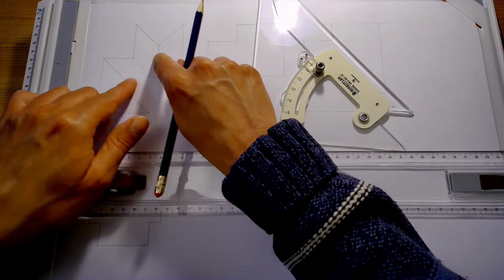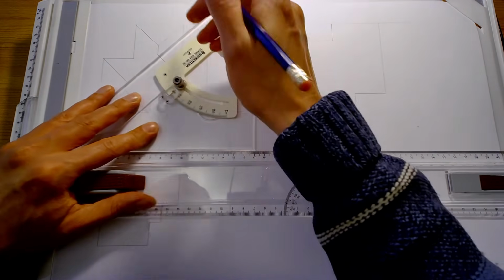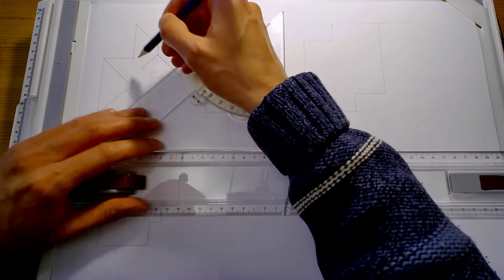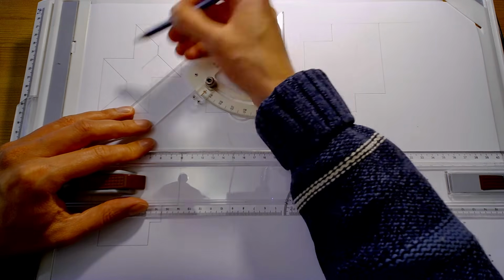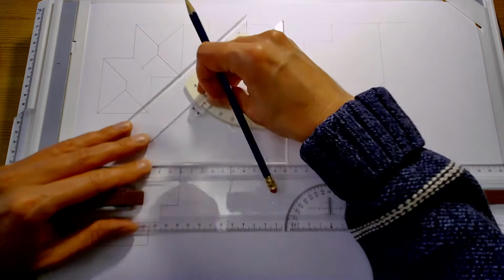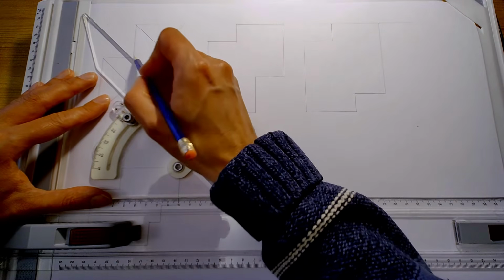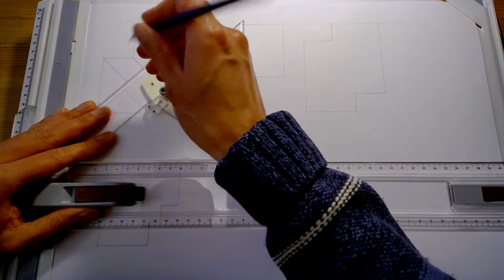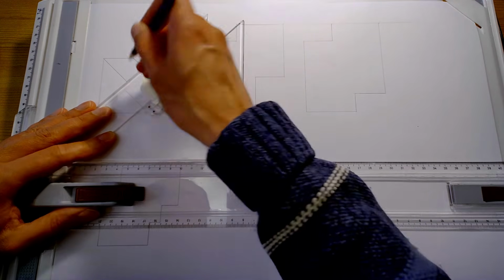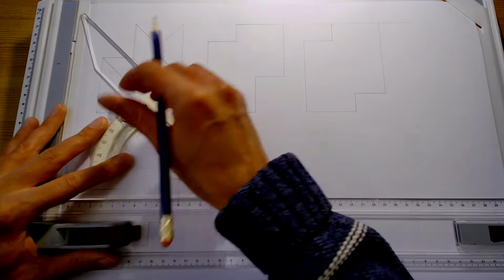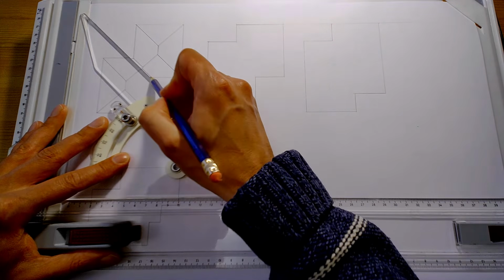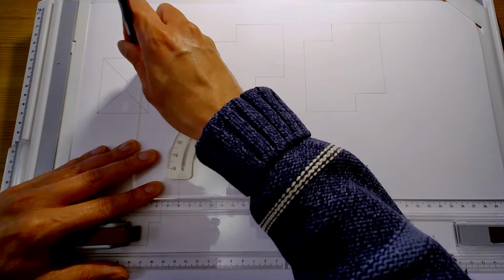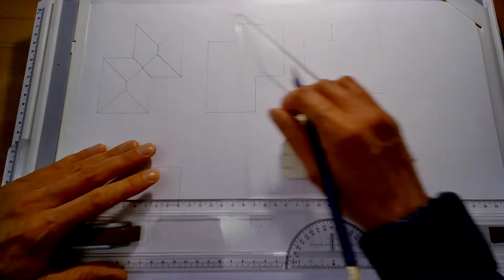Now, as these hips come down, you will see that what we want to do is bring it down until it meets one of these valleys. Now it meets this one first, so that's the one we're going to connect it to. And then we'll do the same on this one by here, bring it down until it meets this valley. And then we've got a short gap between the two where we'll put a ridge, like so.